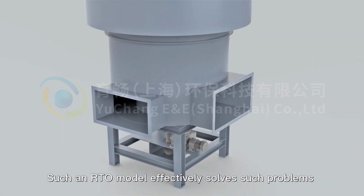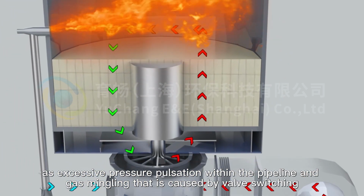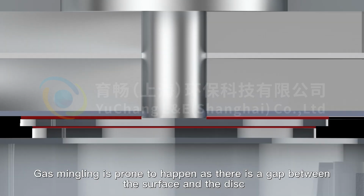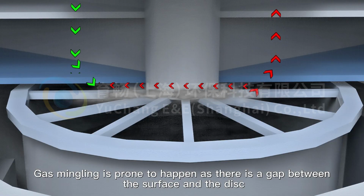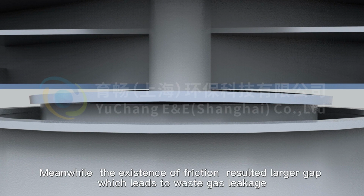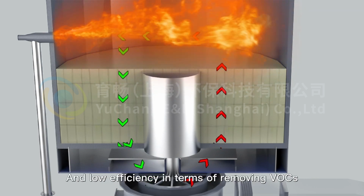Such an RTO model effectively solves such problems as excessive pressure pulsation within the pipeline and gas mingling that is caused by valve switching. Unfortunately, due to its own structural design defects, gas mingling is prone to happen as there is a gap between the surface and the disc. During operation, the disc is prone to distortion owing to fatigue load. Meanwhile, the existence of friction results in a larger gap, which leads to waste gas leakage, and low efficiency in terms of removing VOCs.